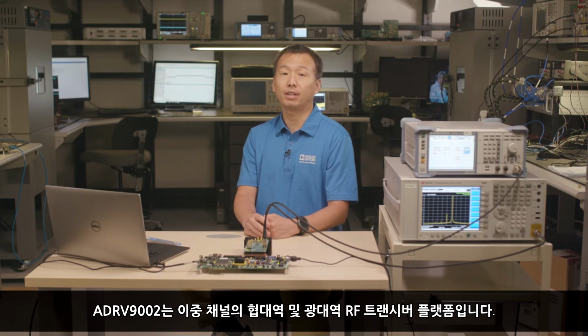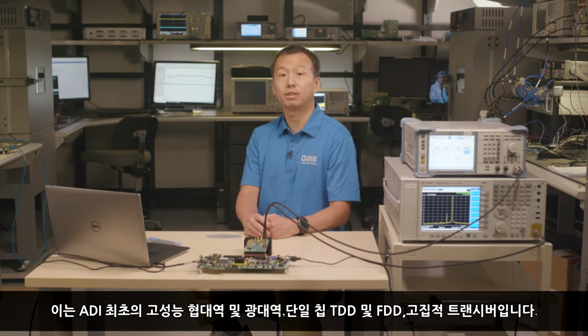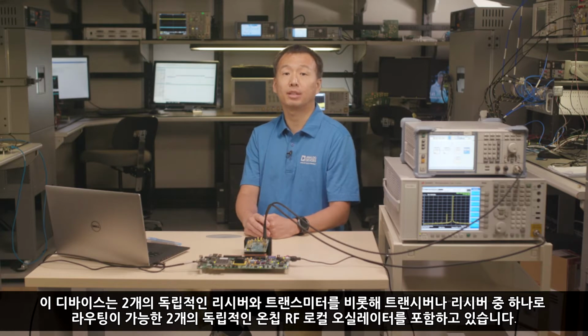The ADRV9002 is a dual-channel, narrowband and wideband RF transceiver platform. It is our first high-performance narrowband and wideband, single-chip, TDD and FDD, highly integrated transceiver. It contains two independent receivers and transmitters, and two independent on-chip RF local oscillators that can be routed to any of the transceivers or receivers.